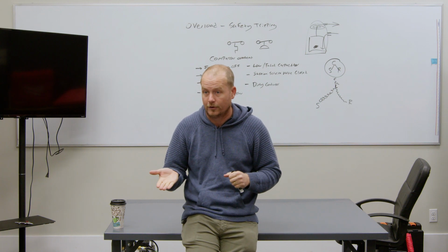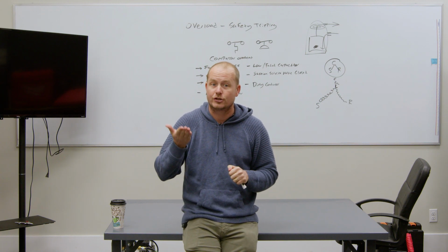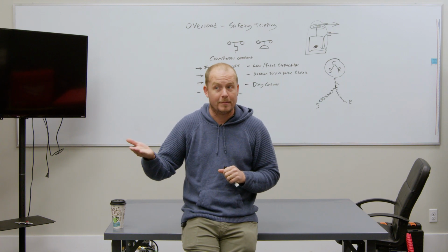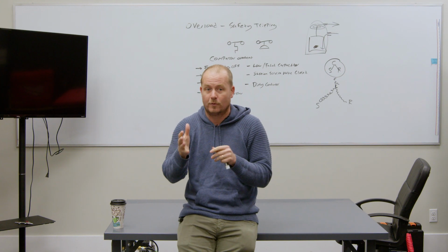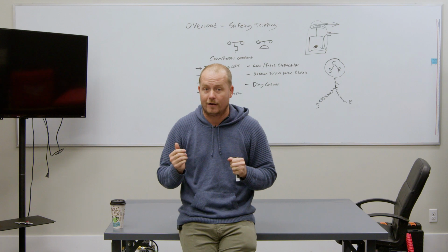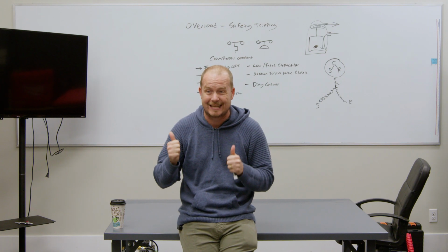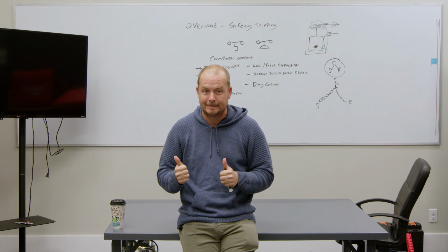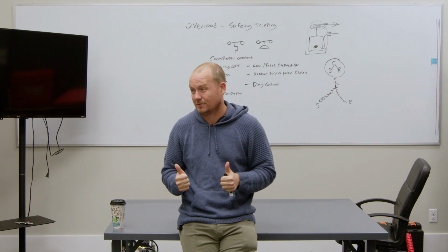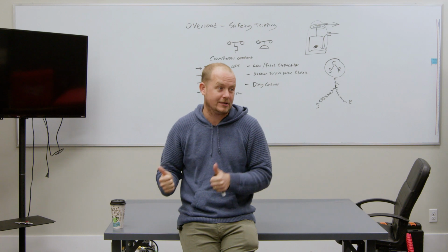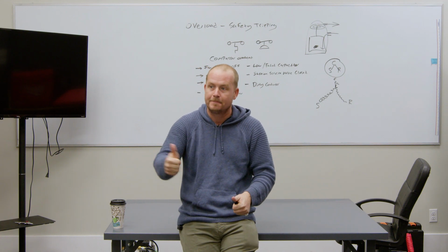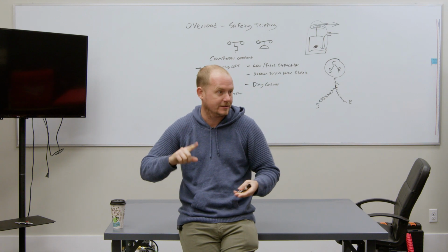Same thing with the thermal overload. If you find a compressor that is truly failed because of an open thermal overload, you still better figure out what else. And this is the reason why I was suggesting what I was suggesting with the compressor, even with the customer, is that we have to have a conversation with that customer, because the odds that that's all that's wrong is pretty much zero. I mean, not zero, but close to zero. That all that's wrong was a compressor with an open thermal overload, because that open thermal overload happened because of low charge, overcharge, dirty condenser, whatever.